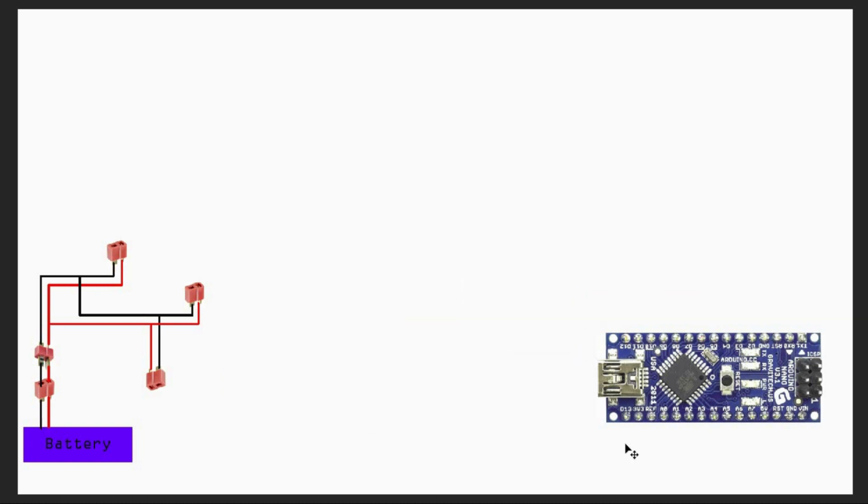So the next one is basically the selector. The selector is like 2 switches in one kind of situation. So I have a ground, and in fact I have 3 pins, but I only need to use 2, because I only need to detect if this is on, or both are off. Then I know which position of the switch is really activated. So basically I only require 2 pins in this case.